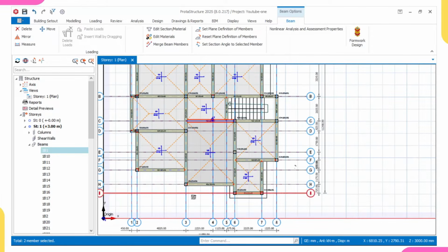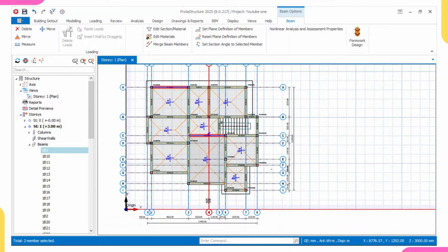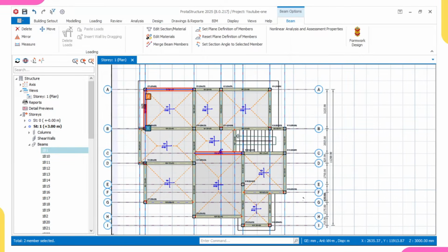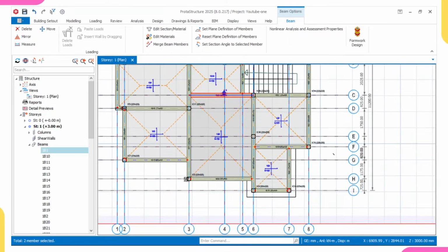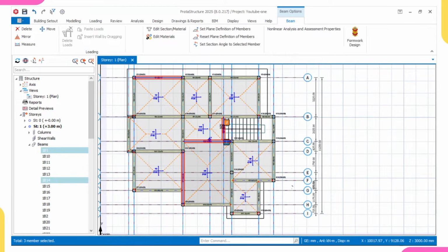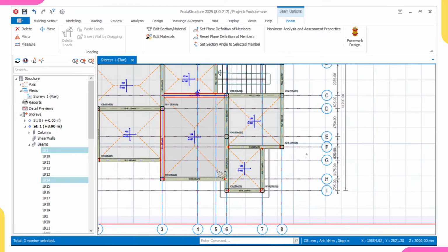I have done this. Then I have selected this. This is a simple supporter, so I'll not hinge. Remember, I'm hinging only I. So let me check: I is downward, so this is simple. I'll not touch it. Then I'll hold my shift key and select this I. I don't know whether you understand it, but if you're not understanding, you can just do it one after the other.